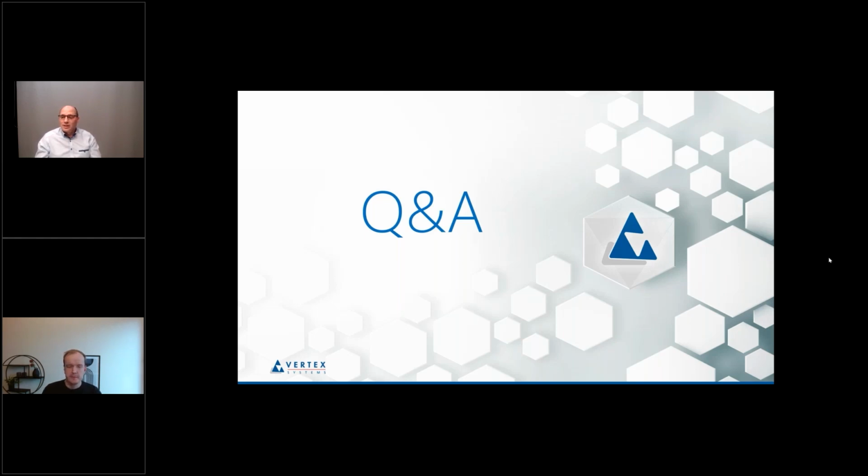Then there was the question, okay Philip, you can answer that. Can I continue working in BD while I send a building into the sync? Yeah, you can do that, but the version that will be sent is the version that was active when you click the button. It will not continuously upload, because it would take so much processing power to do that. Then you can keep working, of course. You can open a new building, you can close BD entirely, you can do whatever you want. It will do it in the background. You will see the little square or dialog window in the bottom right.